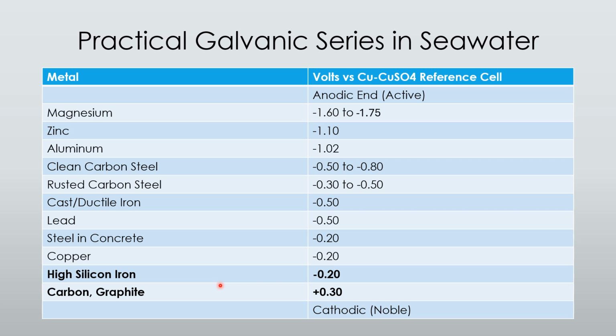Since we're forcing current through these anodes, we need to be really conscious of the corrosion rate, since we're essentially forcing more current through these, and we can adjust the voltage output from these over time. So we want something that's going to be more resilient to differences in voltage.